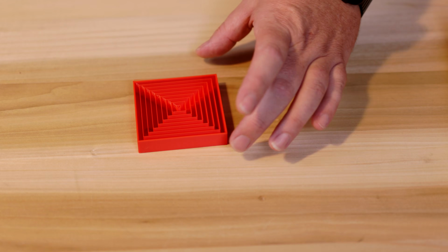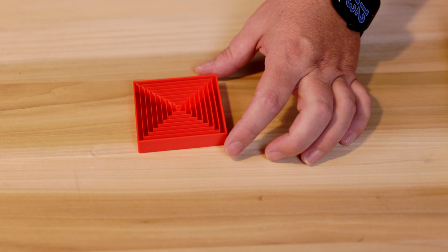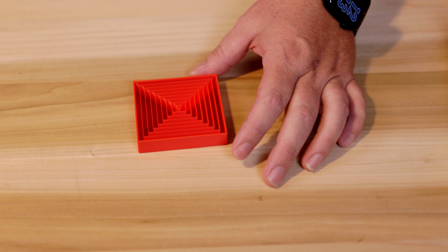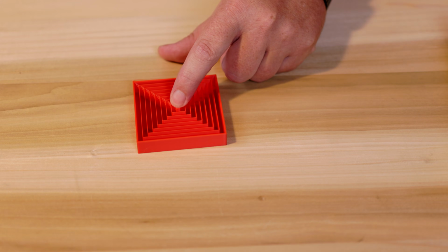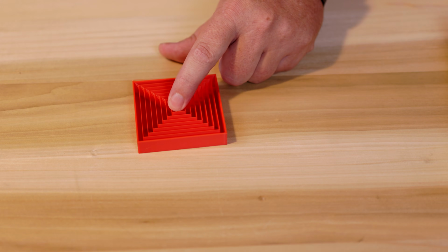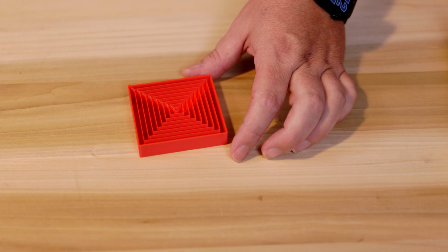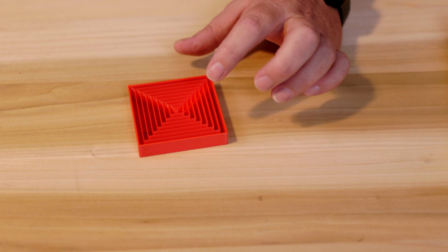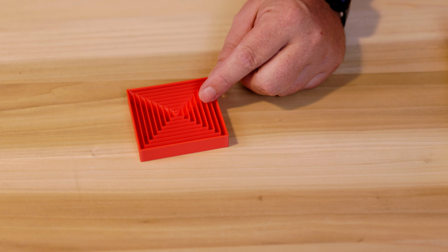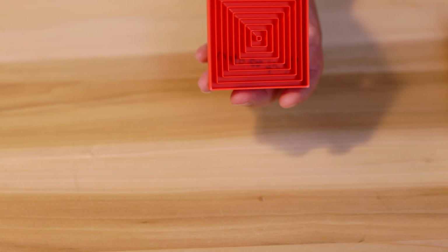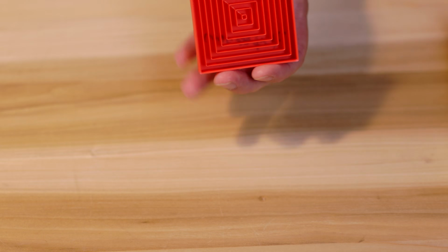All right, so let's see what was printed out. The first one that we'll look at is concentric, and concentric infills are circles or shapes that move outward from the center point. These are ideal for circular objects or when a unique top layer finish is desired. These have a unique aesthetic appearance. That's the pro.